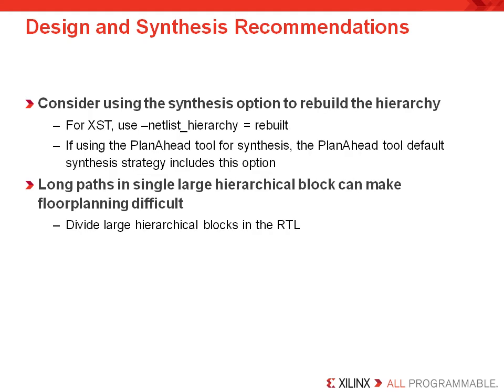Constrain the synthesis engine to rebuild or otherwise preserve the hierarchy in the synthesized netlist. Flattening your netlist may be optimal from a synthesis perspective, but it will make it very difficult to reliably floor plan and constrain your placement. Consider using the synthesis option to rebuild the hierarchy. For XST, use netlist hierarchy equal to rebuild. If using the PlanAhead tool for synthesis, the PlanAhead default strategy includes this option.